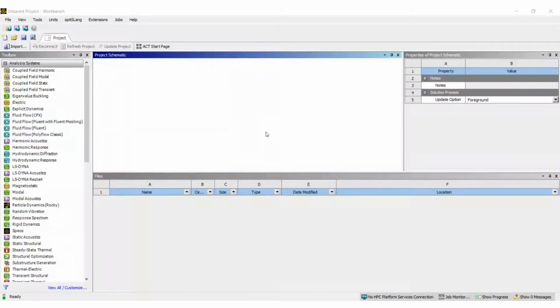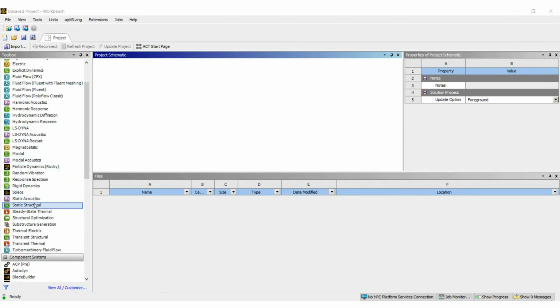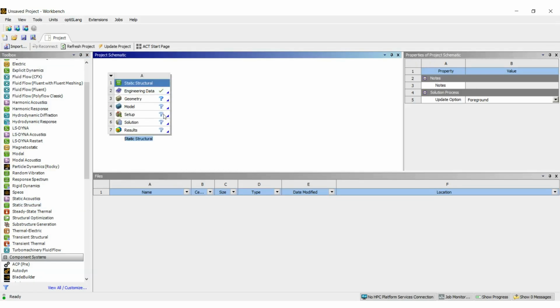Welcome everyone. This video series is intended to introduce you to finite element analysis using ANSYS, and here we are. We are going to start with static structural because that's probably the most familiar to most of you. So we will drag the static structural and drop it into our project schematic, and that will create a static structural analysis object for us. And you will notice we can define engineering data, geometry, model, and eventually we will get to results.